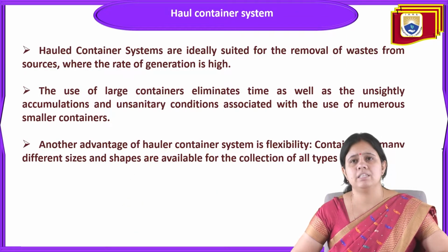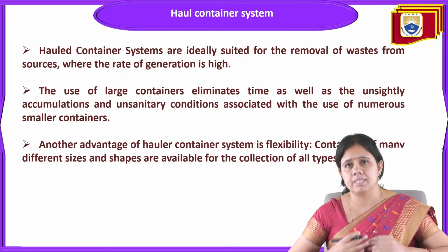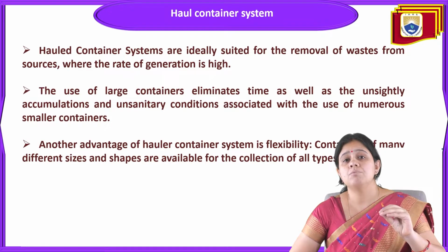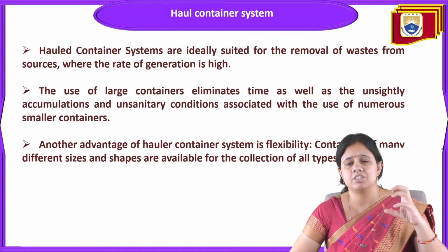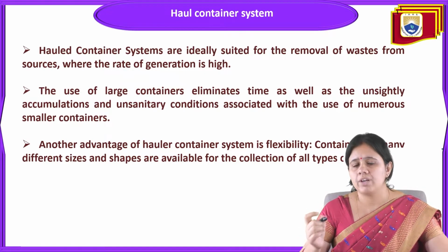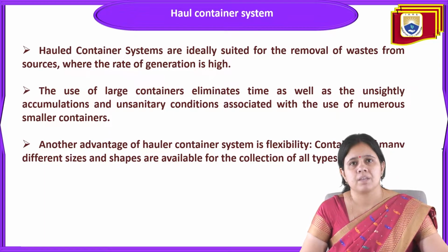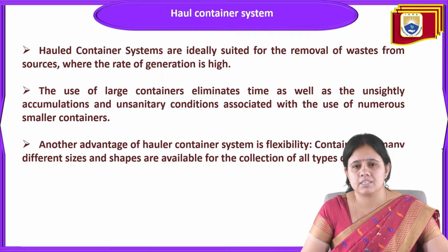Now comes the next point: the benefits and different features of the Hauled Container System. This system is basically suited for the removal of waste from sources where the rate of generation is high, like a metropolitan city, where the waste generation is very high, so that place is suitable for this system. And the use of large containers eliminates time, as well as the unsightly accumulation and unsanitary conditions associated with the use of numerous small containers.